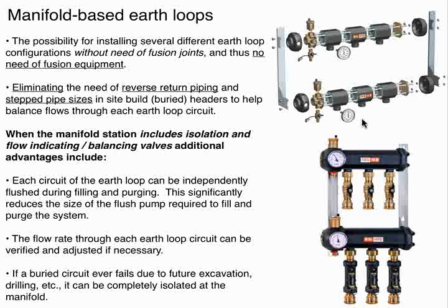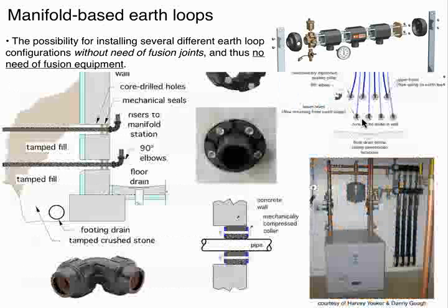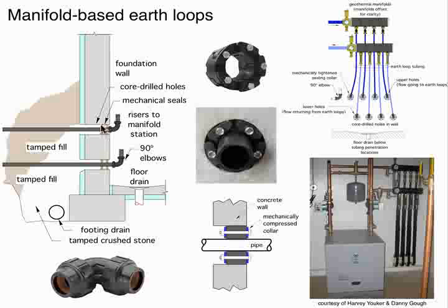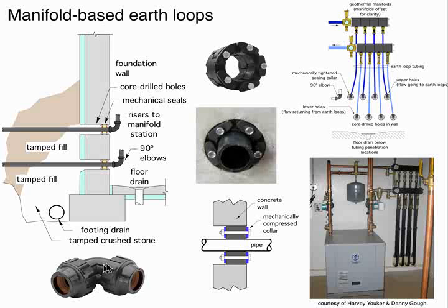Here's an example where the tubing comes in through a foundation wall. It's very important you do a good job sealing that penetration. Just pumping a tube full of GE silicone in there is not a good seal. We like to use these link type seal products. These are compression seals. The pipe basically passes through that inner space. This is a 2.5-inch core drill hole through the concrete. Tighten up these bolts and you get a nice tight seal there.